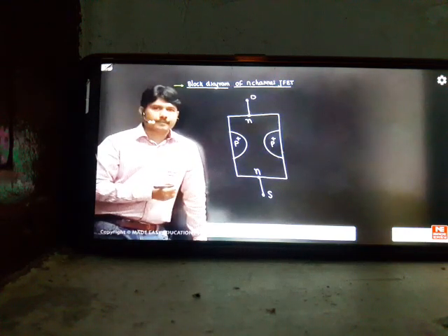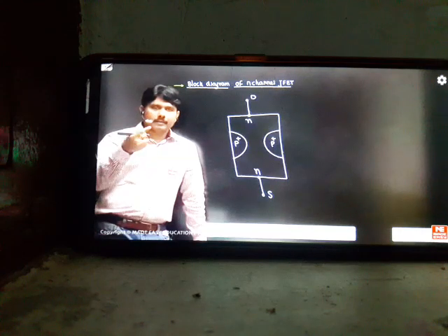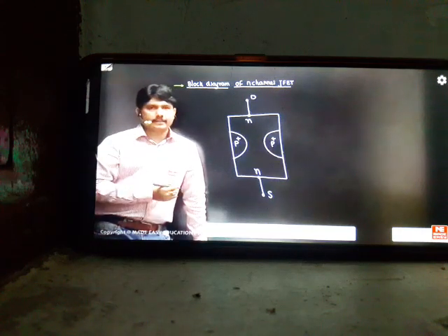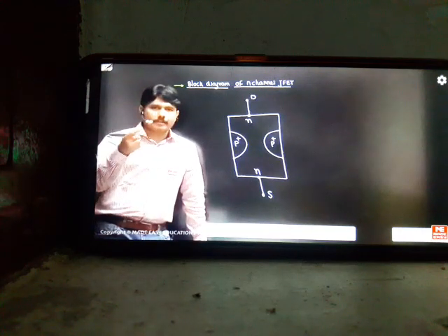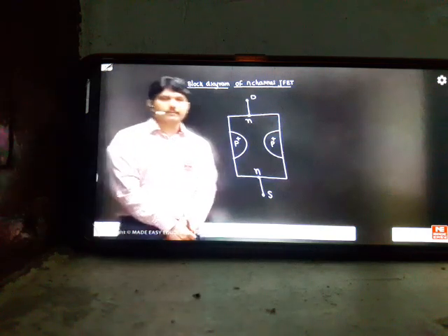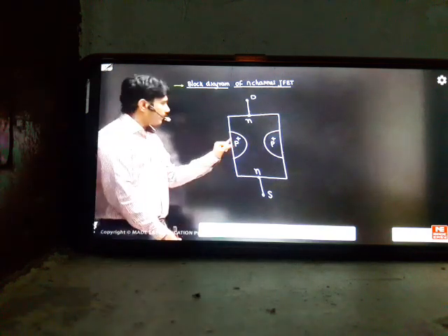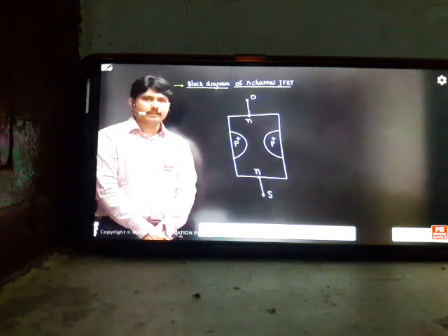Please try to keep this in mind. In any material, if you add some other material, the doping should be more than that. Otherwise, it will not behave as a P-type material in the device. That's why P plus means it is heavily doped compared to the N material. This is one principle which we use in electronic devices. That is the main reason why I kept P plus there. P plus means it is more heavily doped than the N material.